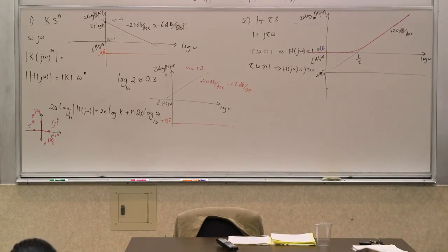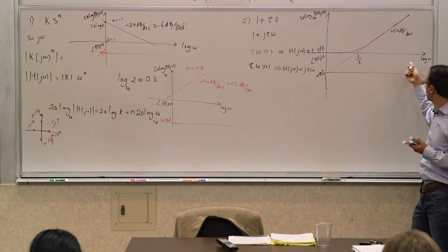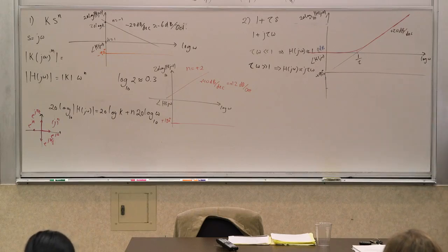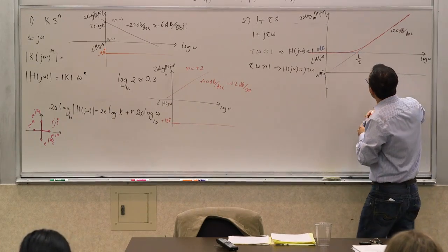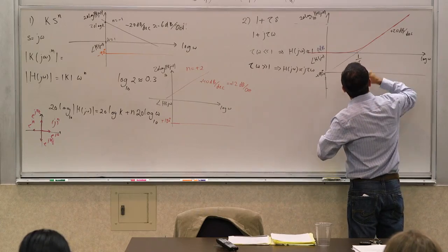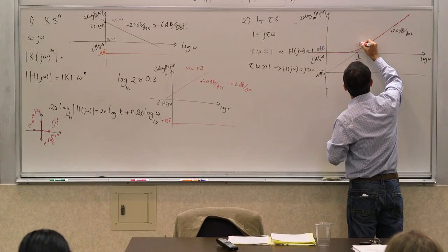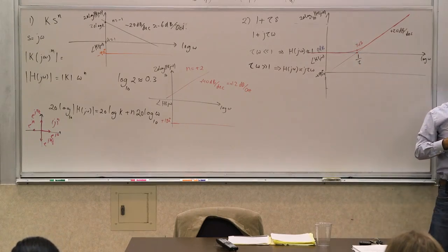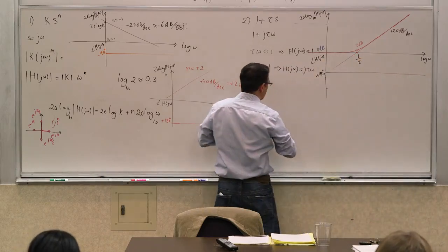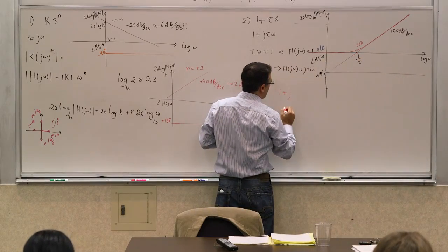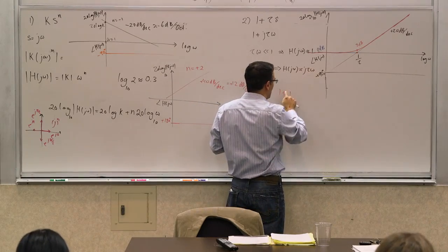It's really a log of that. This is a logarithmic plot, but that's what the frequency is. Most of the time we show it this way, although it's a log plot, just to emphasize what it actually is, right? So this is where the two asymptotes intercept. And then what happens here is that this deviation is maximum at this point, and it's 3 dBs. You can easily show, right? Because at this point, when these two are equal, the thing looks like 1 plus j at that frequency, right? At that exact frequency, this becomes 1. So this becomes 1 plus j.